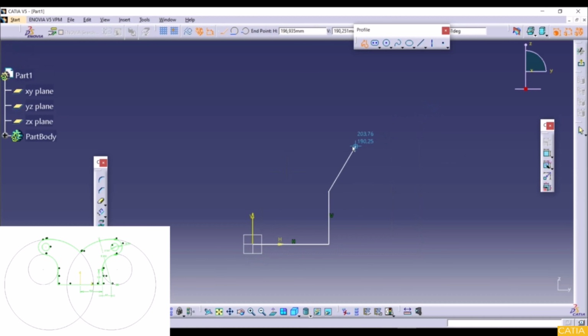And now we're going to switch to the tangent arc. So let's go here and let's select tangent arc, like this. Now move your mouse till this position, like this. Now if you look at the drawing, you can see that between this horizontal line and this circle, we have a tangent relation. And this is what we want. And you can see those two tracking vectors that meet at the center. Make sure that they are perpendicular, like this. Let's click here. So this is our first arc.